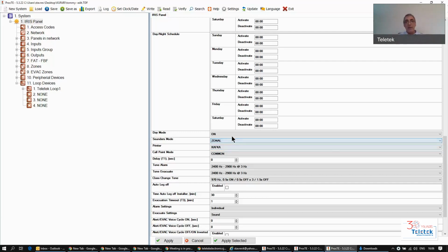In that respect, if I get fire detectors announcing fire or going into fire state in a zone, and the sounders are set to zonal, the sounders from this zone will turn on after the delay you specified previously in the zone. But if you press a call point that is set up to zonal, the difference is that the call point will bypass the previously set delays for that zone. Delays refer to the sounders' action. That's why I'm saying they kind of go hand in hand.